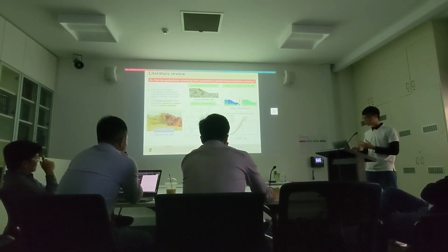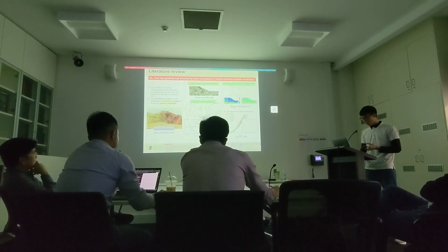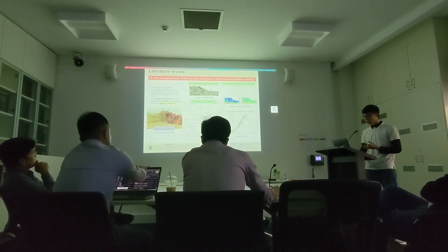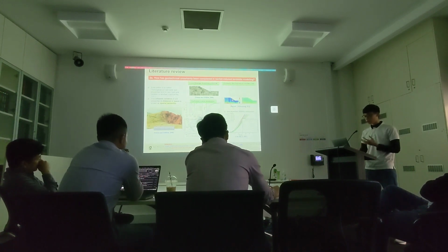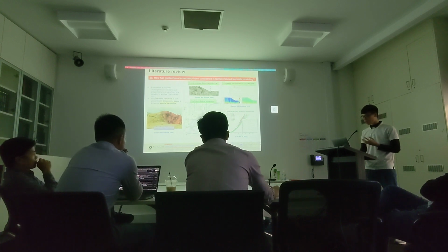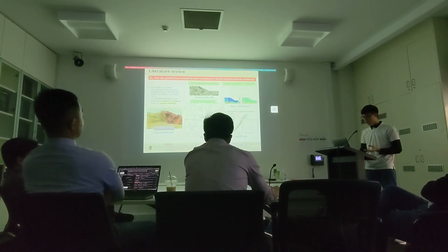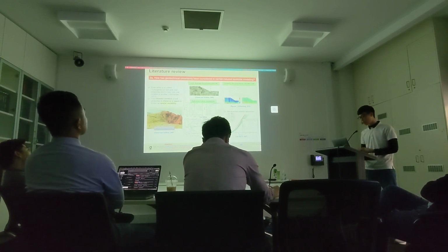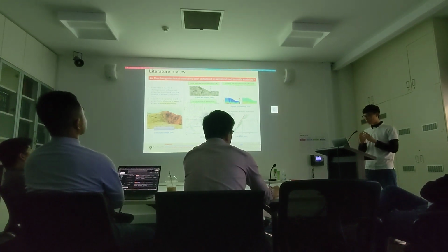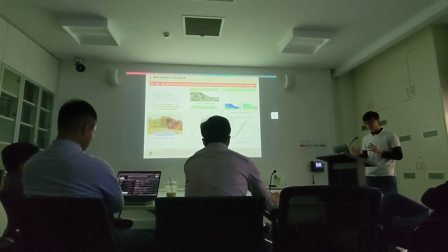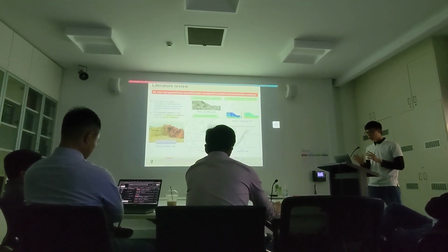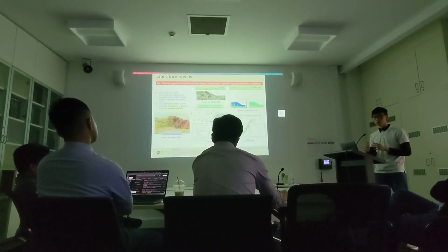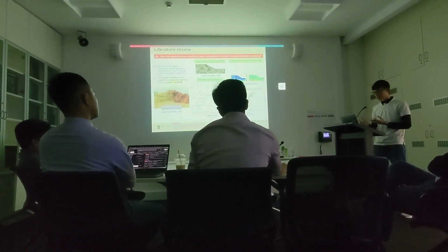In terms of numerical tools, Nguyen and Liu, 2019, used the finite element method with a random field to simulate the rainfall, and then incorporated the water pressure into the LEM method to estimate the factor of safety and the critical failure surface. All of the cases I'm showing here involve small deformation or factor of safety.